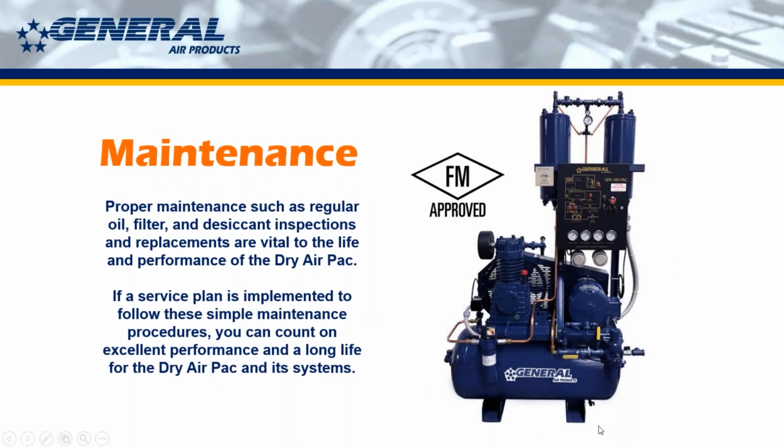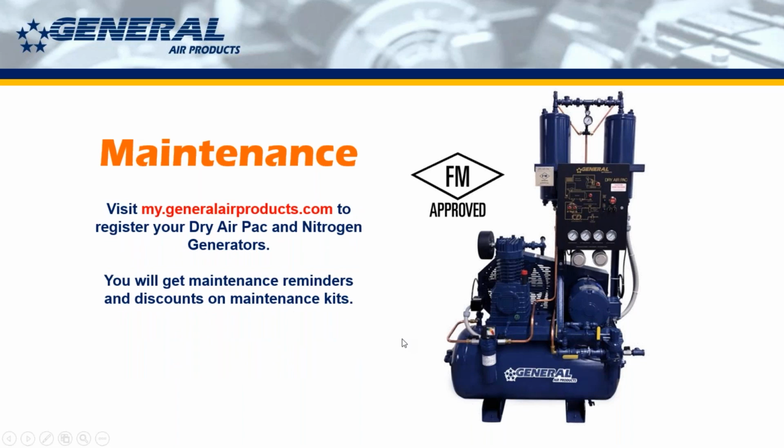Again, this is an air compressor. This bottom part is a lubricated tank-mounted air compressor, so all of the maintenance that needs to be done with that compressor is what needs to be done on a dry air unit. But then you get up into this top part here, which is where we have the desiccant and where the drying occurs. So that adds some complication to this. But the intake filters, there's a pre-filter down here. There's these mufflers here. All of these things should be looked at from a maintenance standpoint, so that they're cleaned out.